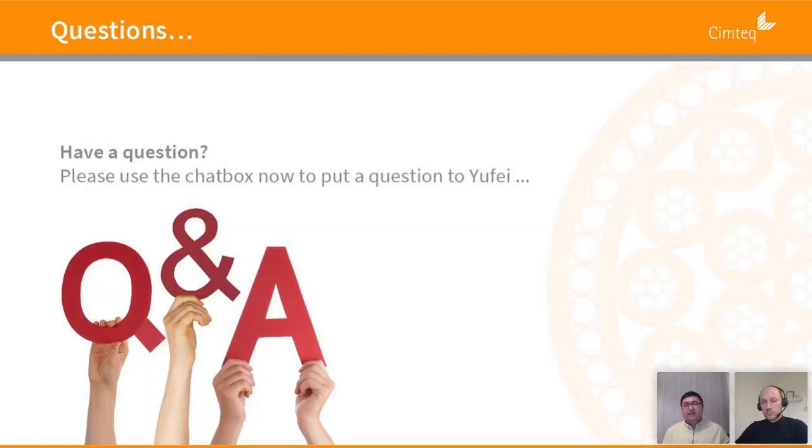And yes, MES is a very important one because it's recording all the data from the shop floor. If you want to do planning, good, use machine learning, you need data from MES. If you want to do quality or even find maintenance patterns, you need MES to record the maintenance records for you. Then you can use them. So basically, MES records everything that happens on your shop floor. Then after you have this data, we can talk about how you can use it in smart ways. But without MES, you can do nothing, because everything on paper cannot be smart, and you cannot apply big data or machine learning models.